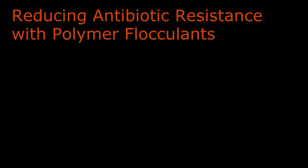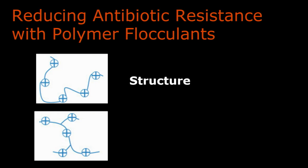What we've learned is there are antibiotic resistance genes that, if untreated, are recycled through the treatment process. And we know that treatment plants use polymer flocculants. But by choosing the right polymer structure and optimal dosage, this can be a way to reduce the spread of antibiotic resistance within the treatment plant.